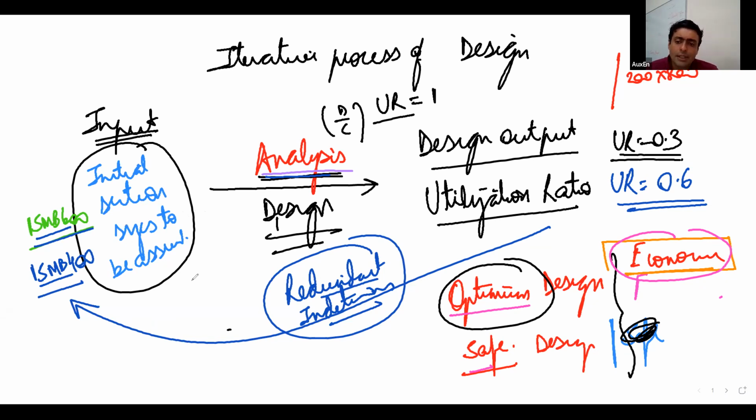Mainly the bending moments change. So to take that effect into account, we will have to go back and rerun our analysis. Is it clear? This is very important. Whenever you change any size, you must always rerun your analysis. Why? Because a change in stiffness leads to changes in analysis results. Extremely important thing to understand, and I'll be repeating this quite often henceforth.